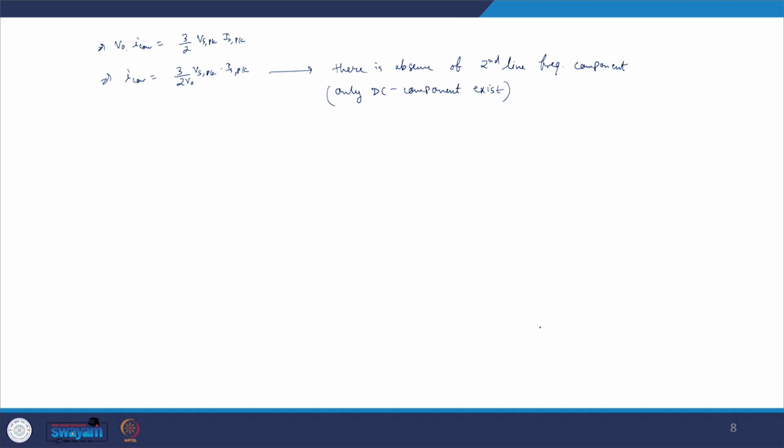That is the reason why this will result in small capacitor size for 3 phase AC to DC converter, which was not the case when we use 3 independent single phase AC to DC converters, as all the 3 single phase converters will have the second line harmonic voltage ripple at the output capacitor, thus requiring 3 large capacitors to keep the output voltage ripple within the limits.